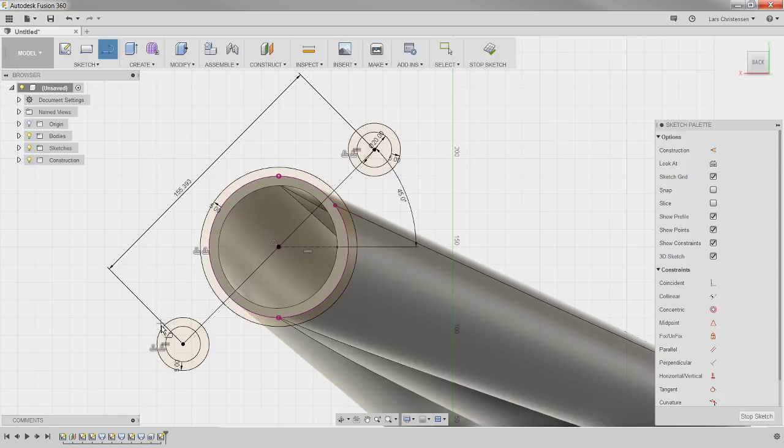Line. If you hold down shift, it will include the tangency. Like that. Hold down shift. Then click on the circle. Click over to the line. You'll find the tangency. Hold down shift on the circle, and it should find the tangency, not the midpoint.